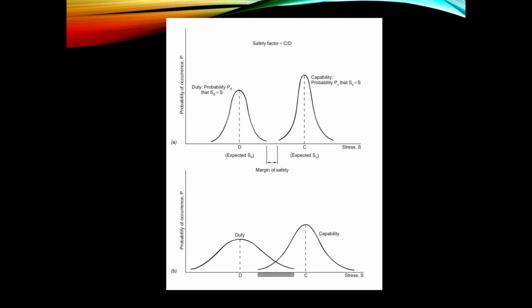On the right side, you see the design or expected capacity in the center there, where it says letter C, and you're anticipating that there could be some variation for the as-built bridge. And so if you look to the left tail there, you want that to be higher than what the maximum expected load is.